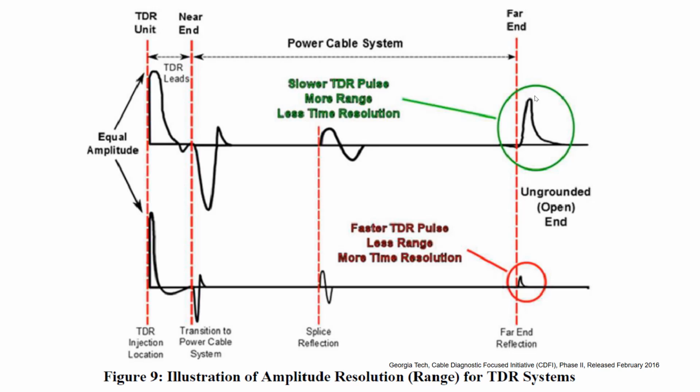You will see the same kind of polarity, but with attenuation. This is the signal sent at the input end, but see how the signal has changed. The width and the height have changed here. Now similarly, this is a faster signal. The faster signal gets attenuated more, unfortunately. In the faster case, you have more time resolution. Time resolution means the resolution in time scale or distance scale also. This has more time resolution, but it reduces the signal strength, it attenuates very fast actually.